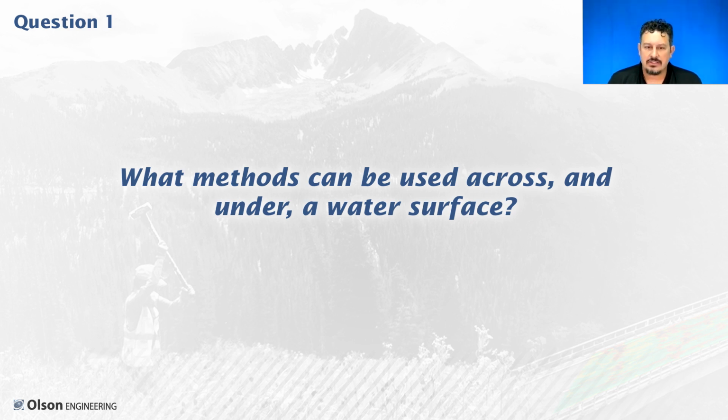It's not quite as flexible as a surface resistivity survey because we can't change the spacing between the electrodes as easily as we can on a surface survey. So if we have a depth range, we can have a custom cable made to get the range of interest covered. You can do EM surveys that way. Occasionally those are done.